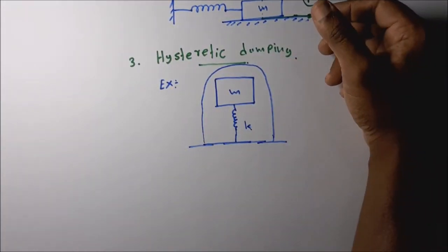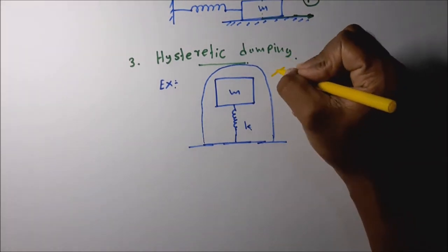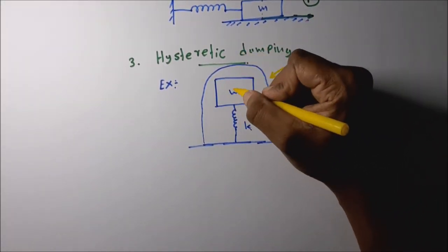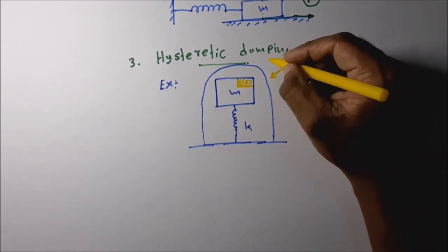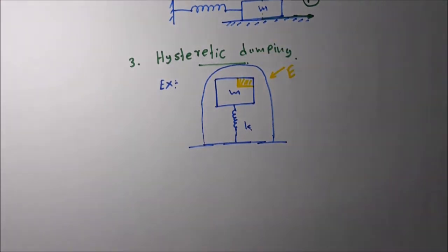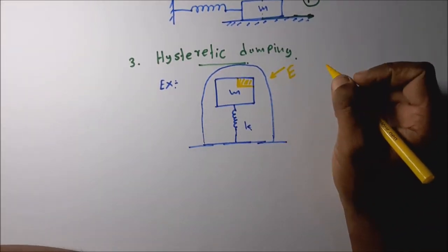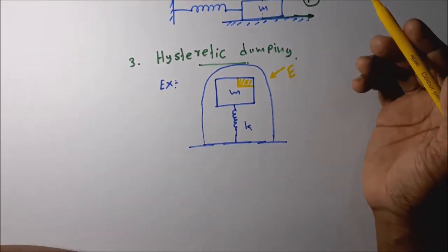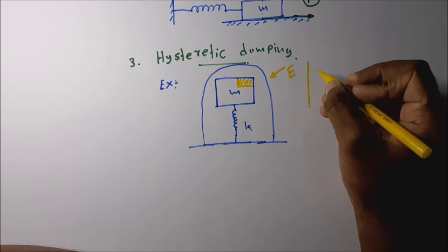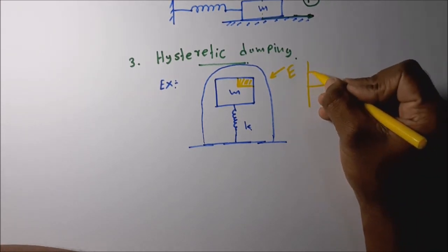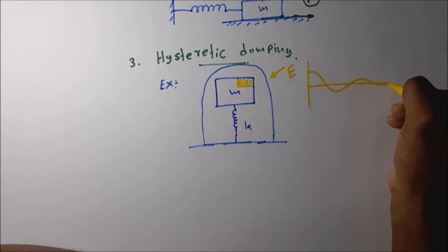So let's take that we give a certain energy to the system through a magnetic pulse. There is a ferrous metal part, and from the magnetic pulse we give certain energy to the system. So what can you say about the vibration of the system? Does it vibrate forever? No. Why is that? How is the energy dissipated from the system? The system amplitude gradually diminishes. It vibrates with a diminishing amplitude like this.